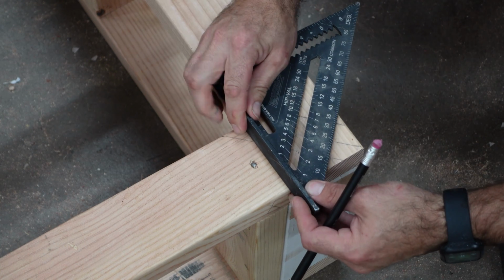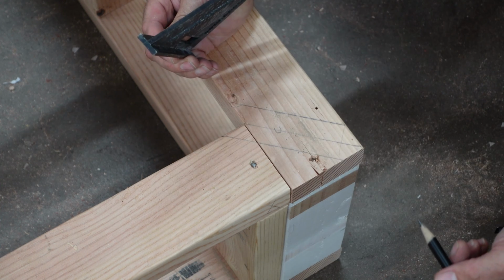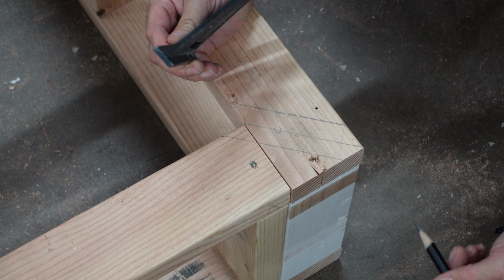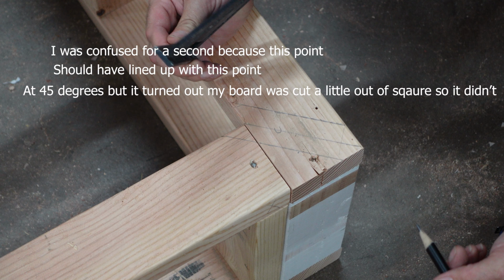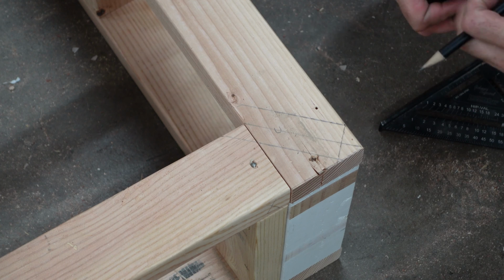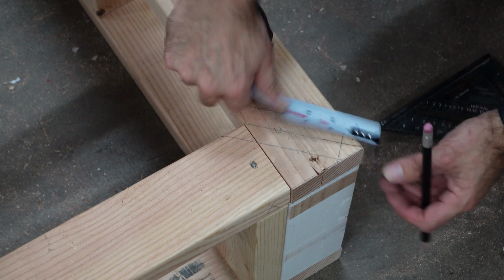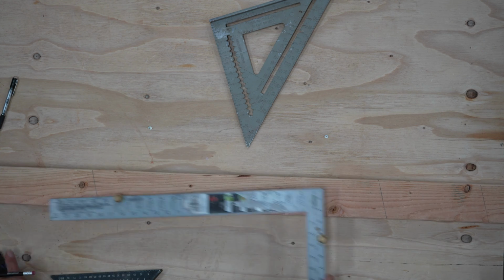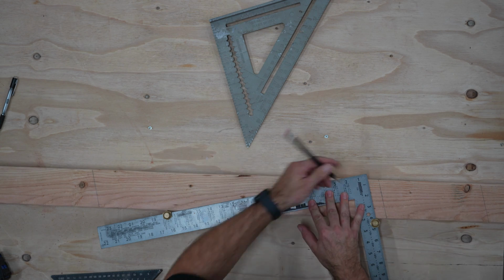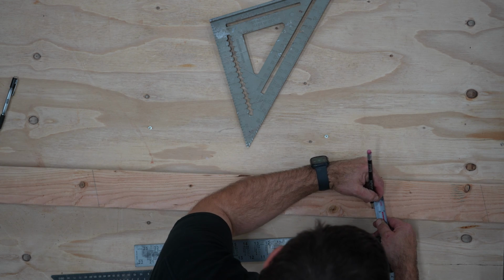Now we need to make a seat cut. The length we came down from the top of our common rafters in the last video was 2.5 inches, but we can't come down that distance from our line that marks the outside of the wall because it isn't the same point as it is on the common rafters. We need to make a mark on our wall at a point where our hip touches the outer wall at the same point where the common rafters touch the outer wall, and make a line from there perpendicular to the travel line of the hip rafter. Then we measure back to that point from the outer corner of the wall. This is how far back we need to measure from our plumb cut that represents the outer wall. So I measure back and make a new line. This is where I can measure down the 2.5 inches we want for the seat cut.